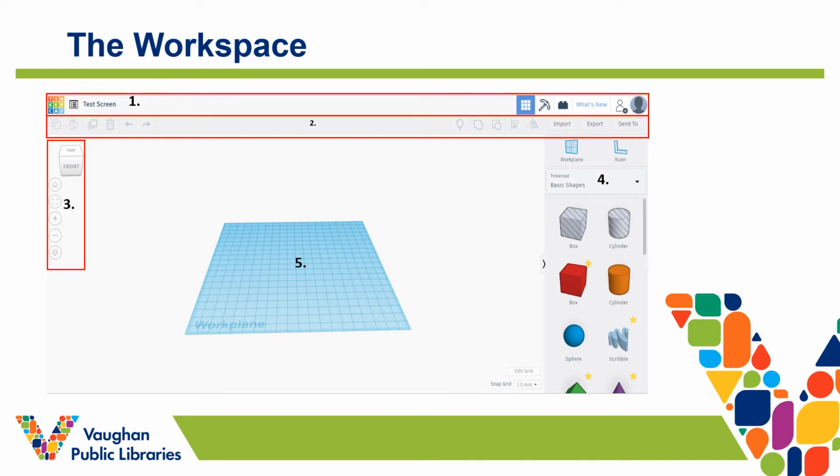On the right-hand side of the screen is the Palette, Section 4. Here is where you'll find the shapes and objects you'll be manipulating on the work plane to create your projects. The last piece is the main work area itself, known as the work plane. Only objects placed on the blue grid are considered part of the project. If you export your project with 3D objects that are not on the blue grid or attached to it in some way, they will not be exported.